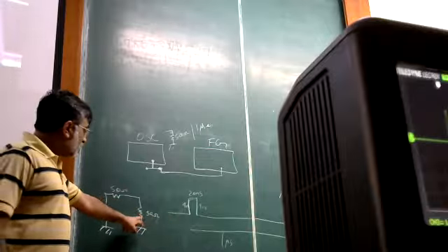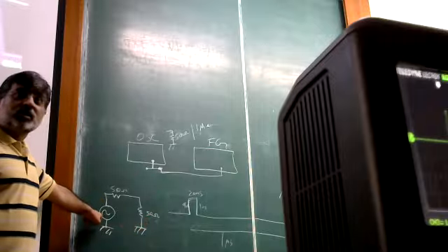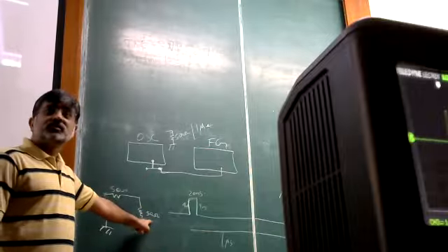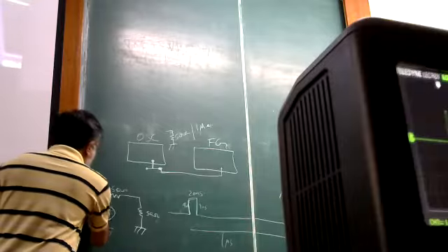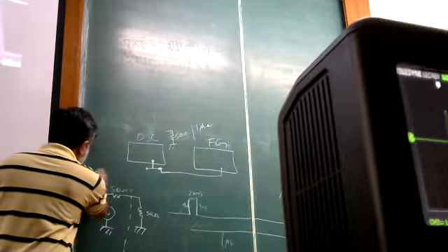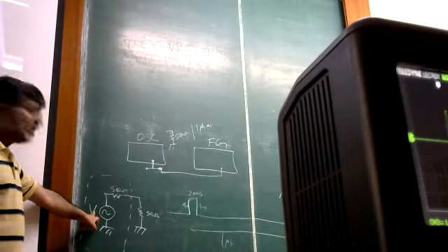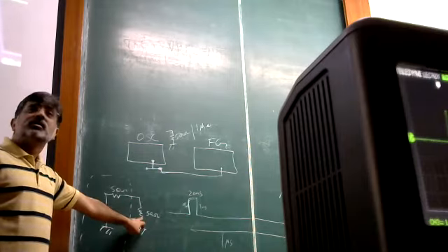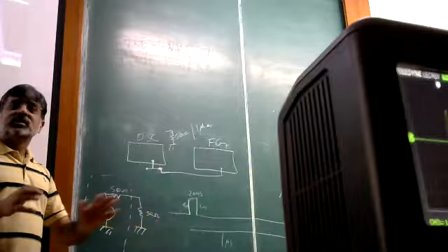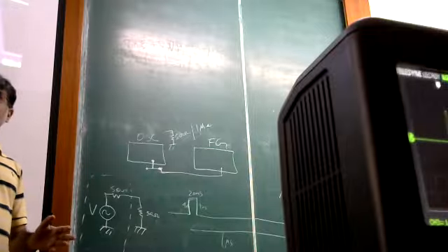It's because in order to get a certain power here, the voltage here is not going to correspond to only this voltage drop, right? Because there is a factor of 2 division. Whatever voltage you have here for this ideal voltage source model, this voltage needs to be twice the value you need here. So this is more on the practical side of things, that if you deal with these instruments, it can actually cause mistakes if you're not careful about the setting.